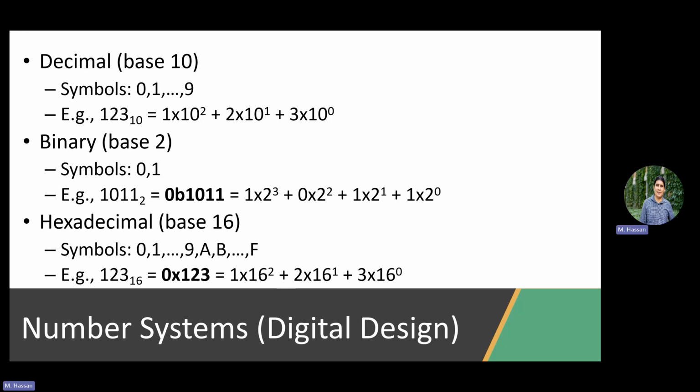Okay, a few slides then. Yes, you said dynamic memory allocation is not really used, in what sense? It is not allowed in highly safety critical systems. Up until now, the standard disallows them. It tells you that your memory usage must be static, just to have a defined behavior.